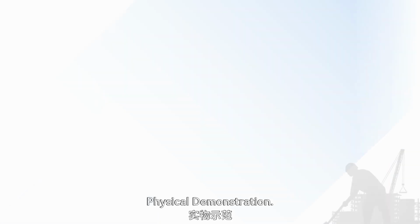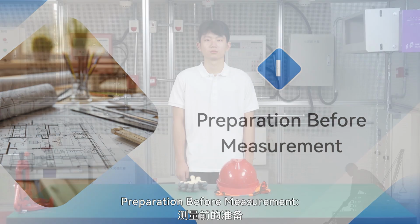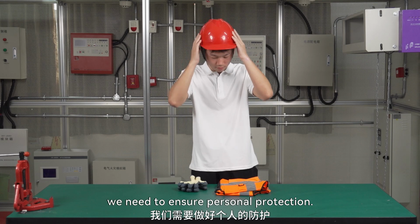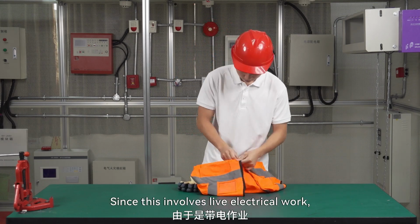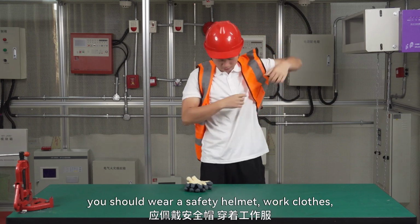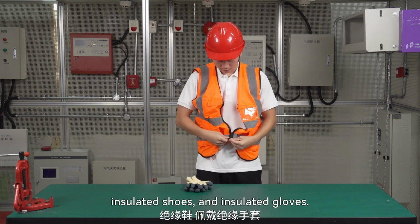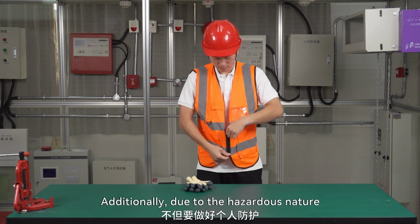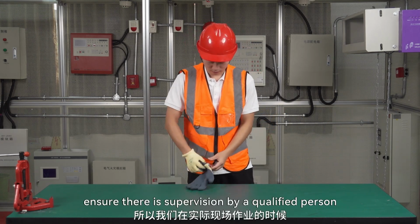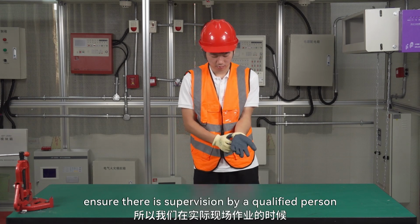Physical demonstration. Preparation before measurement. Before using the Megohmmeter, we need to ensure personal protection. Since this involves live electrical work, you should wear a safety helmet, work clothes, insulated shoes, and insulated gloves. Additionally, due to the hazardous nature of working with live electricity, ensure there is supervision by a qualified person during actual field operations.